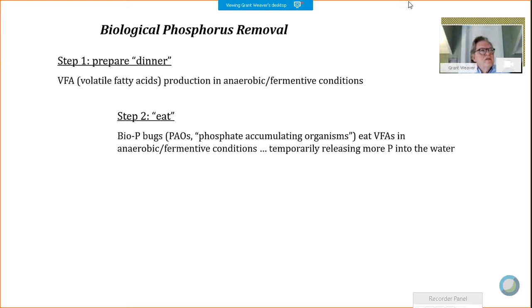If we have nitrates in our wastewater that go into a low oxygen environment with volatile fatty acids, the bacteria that remove the nitrates will eat the majority of the volatile fatty acids. So unless we have a surplus, the phosphorus removing bacteria will be left wanting. So we'll get into that and some of the design technologies. Engineers have come up with ways to work around that.